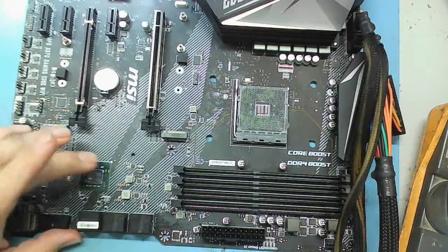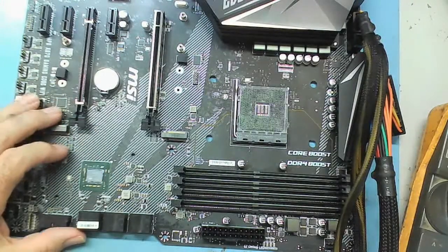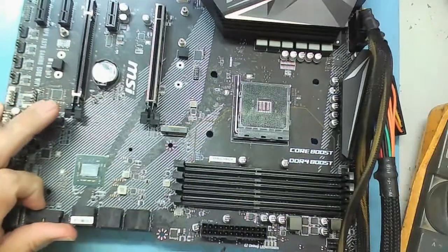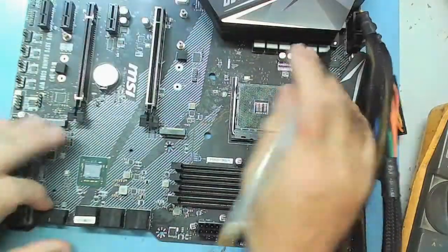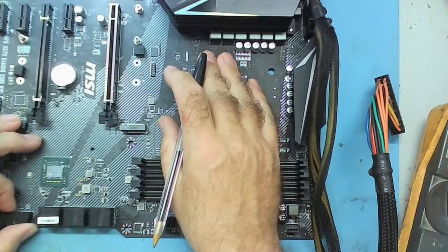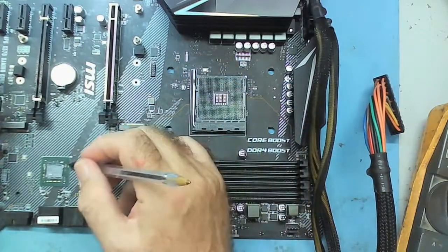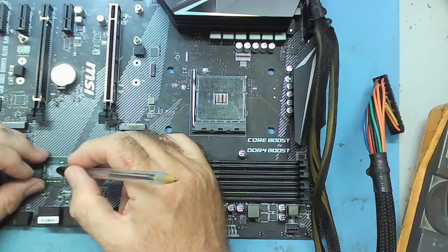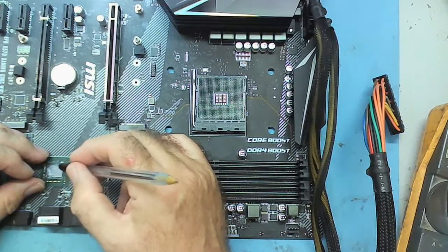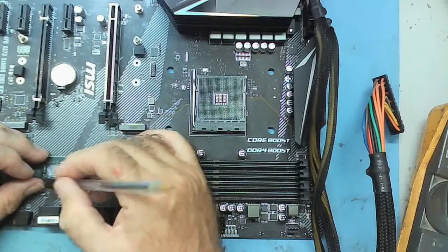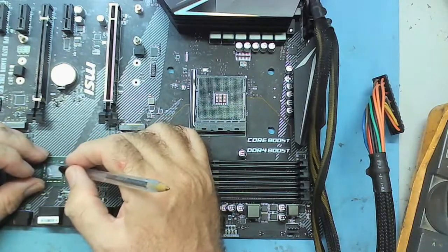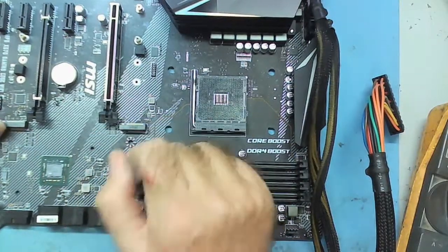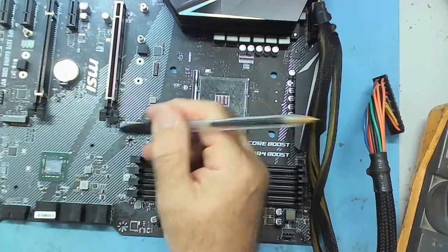So that got me suspicious straight away. But without that experience, and then obviously being able to compare with a good board, could you find it? Yeah, you could. You'd have to be suspicious of those voltages, and I'm hoping now from what I've taught you that if you ever see that, you're going to be suspicious of those voltages, yeah? But what if you're suspicious of the voltages but you're not sure, I wasn't sure, and you haven't got another good board? Well, good, same chipset.